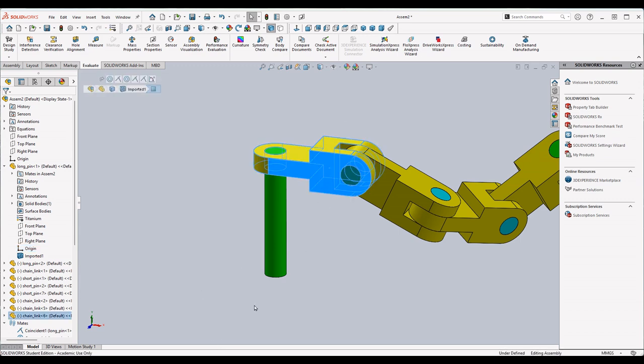Sometimes you have to tell this face to be parallel to the front plane. That way it's pointing in the X direction. Like on what I did last night, and what I don't want to post a super long video for, I actually had this pointing the other way, in the negative X direction, which gave me wrong values for everything. So just pay attention to things like that. If you have the right numerical value but it's negative, that just means it's pointing the wrong way, so understand your coordinate systems. So this should be able to be put together really easily.